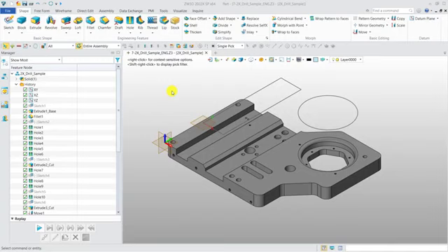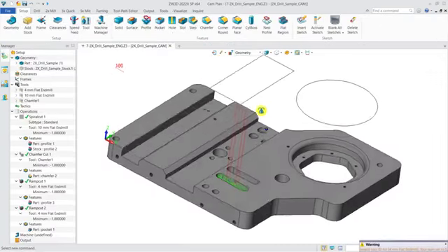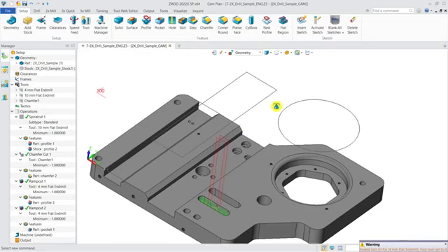Okay, now we're back to GW3D to show you the sketch management. Here I'm in GW3D CAD environment. These 2 sketches were created in CAD environment. And I can go to the CAM plan by clicking this little icon. Then you see the sketches created in CAD environment were inherited to the CAM environment. And here are the functions for the sketch management. You can insert, activate, blank, or delete sketches.